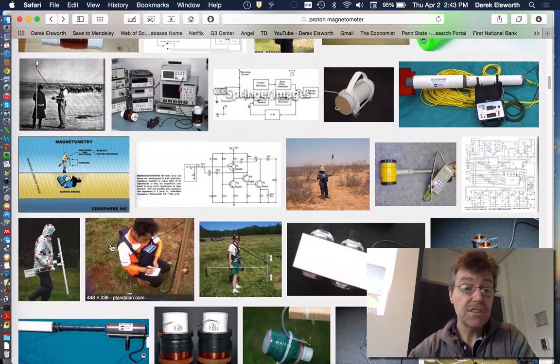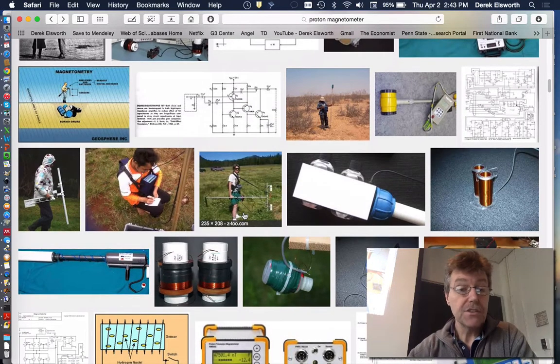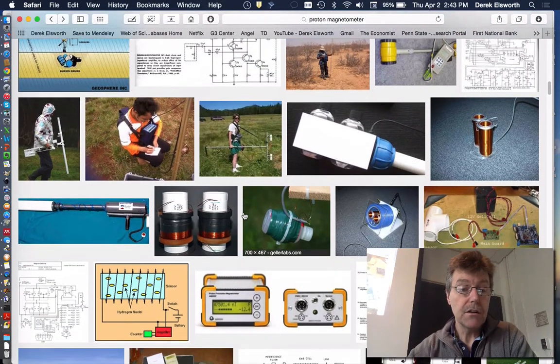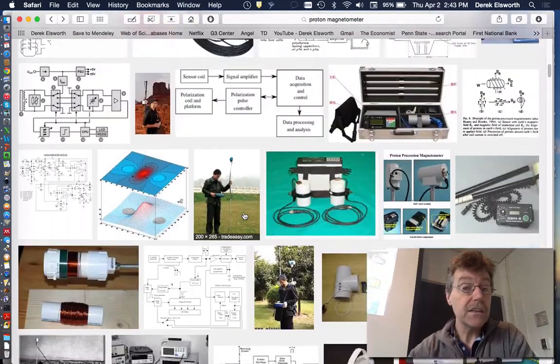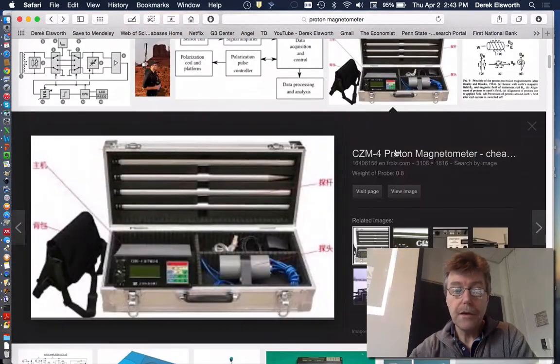Yeah, they're just an antenna. So you walk across the field with some form of antenna. You don't have to stop. It just measures it continuously, not at as high resolution as if you use a regular magnetometer, which is just a box that you put on the ground, which I would suspect that this might be a more accurate one that does a reading at a particular location.